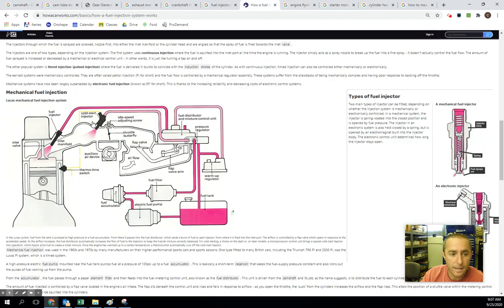And then it's coming in and saying, okay, my camshaft is here, spray in cylinder 4. My camshaft is here, spray in cylinder 1. Spray in cylinder 2. Spray in cylinder 3. Now go back to spray in cylinder 4. And it's constantly doing this, thousands of times. I mean, this is in milliseconds, so it's constantly doing that. But based on that position, it just knows where to spray fuel, and that's how it reads that.